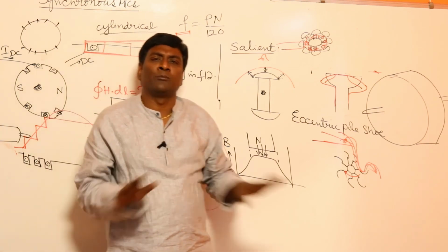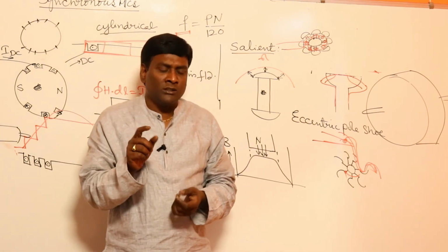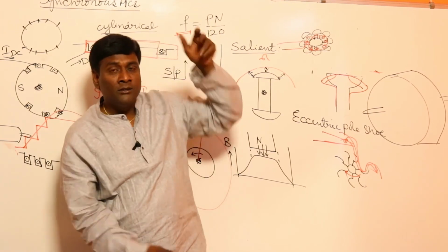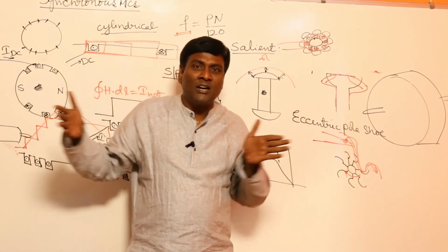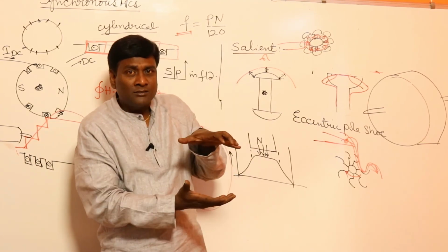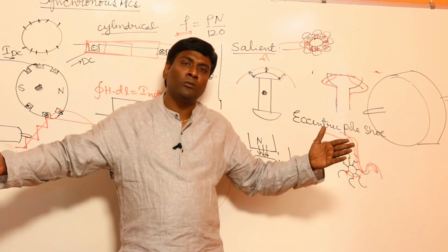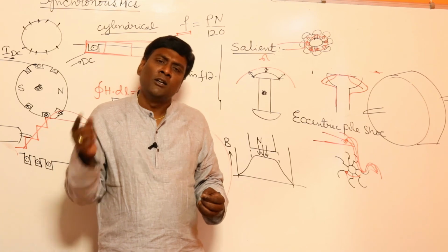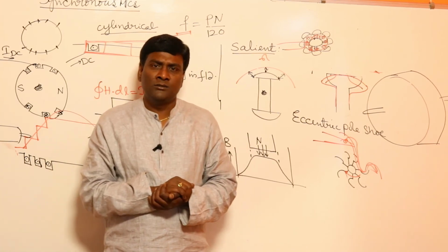So the conclusion is damn simple. What is the conclusion? Salient pole is meant for hydro turbines, diameter is big, and active length or length of the shaft is going to be less. And the cylindrical rotor, diameter should be less and length of the shaft should be more. It is supposed to be maintained at higher speeds, meaning we are going to use turbo alternators or steam turbines.